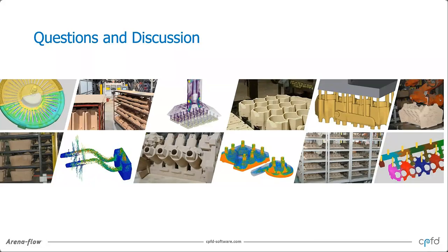Thank you. And the last one that I have here is, how do I set sand flowability for my process? Well, maybe I'll start, and then Thomas, you can add more commentary if necessary. One of the big differences for different processes, shell sand, when it's not heated, flows quite well. Cold box is obviously sticky. Organics tends to be stickier. This is not a scientific term. Somewhat is. But then you have other variability, right?